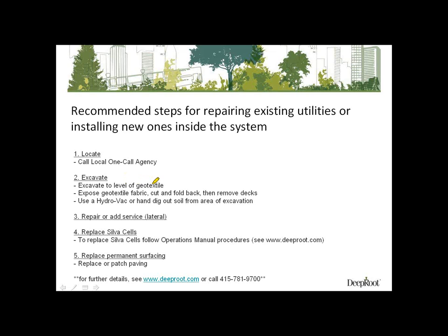If it's a shallow utility, you can remove the deck and then use a hydrovac or hand dig out the soil. Remember, that soil is not compacted very heavily, so it digs well. Then you can expose that utility. Do your work and then repair the Silva or replace the Silva Cells. And we'll talk about that a little bit more, the different options for repairing or replacing or restoring the Silva Cells.